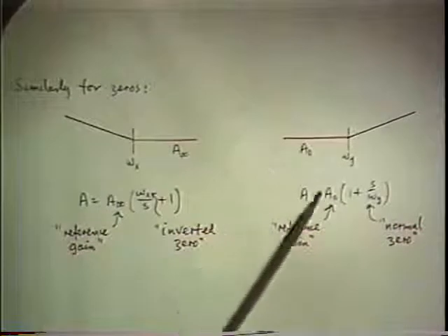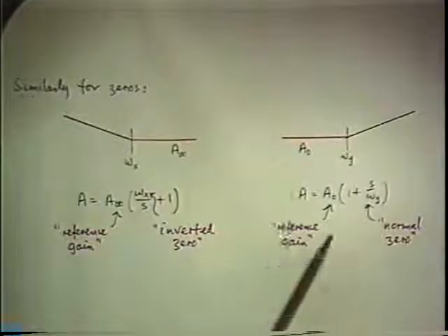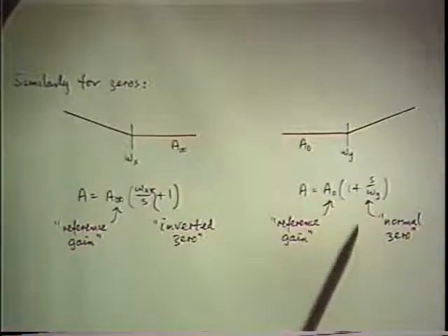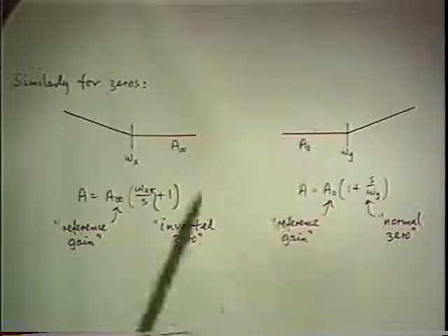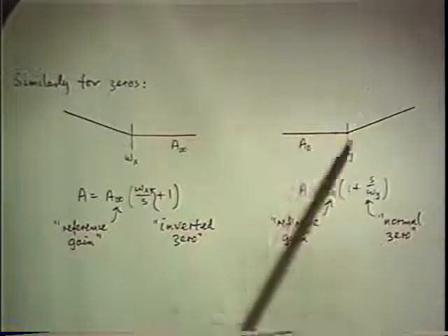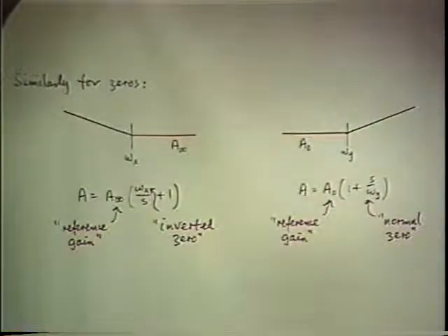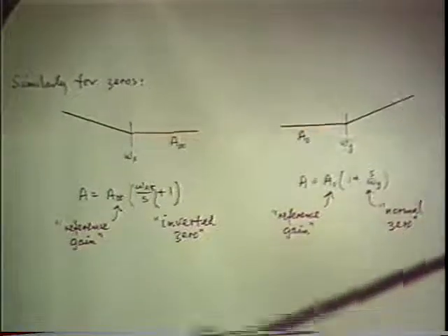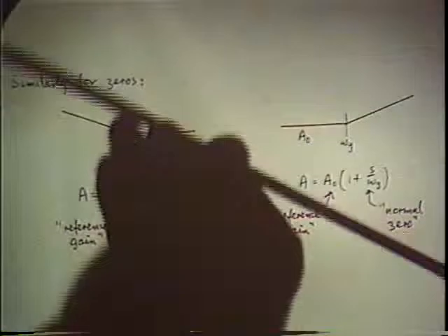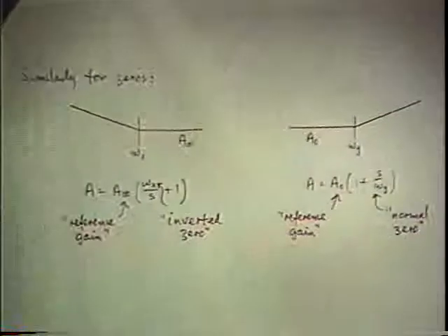Inverting the function, in this case the left-hand side, which is the vertical axis function, which means moving that factor from denominator to numerator, changes the sign of the logarithmic unit, which is equivalent to a vertical inversion. So all that happens is, as normal, a zero is a concave upwards corner instead of the concave downwards corner that you had for the pole.